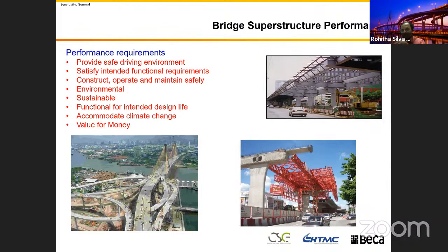If she's interested, I can send her the fib International document about pedestrian bridge vibration. If you read through that document you can get many inputs. For example, in the Australian standard AS 5100 part 2, they clearly define what frequency range we need to consider when designing a pedestrian bridge.